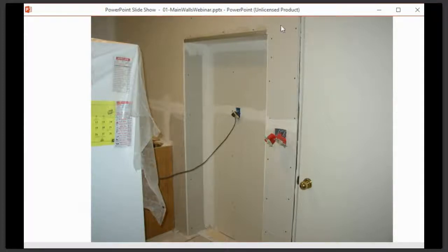And again, sometimes you have to do things like this for a practical purpose. So, for example, if you're putting in kitchen units and you have a wide fridge or an extra large fridge and you want it to sit flush with the units, you may need to create an inset so that the fridge freezer, etc., can go straight back into the wall and everything can sit flush. So the only way that you can do all this is by planning exactly how you're going to use the space and what you want in it.